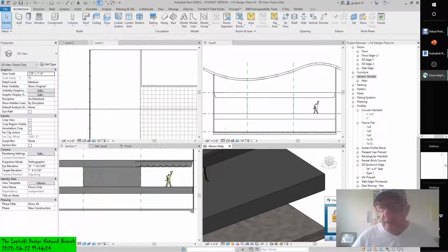Okay, modeling thick finishes. Thicker finish materials such as tiles, stone pavers, or terrazzo can be applied as unique floor types and modeled where required. For large areas of finish, such as a public atrium or airport terminal, you can assign these materials within the layers of a floor assembly, and we'll do that first.